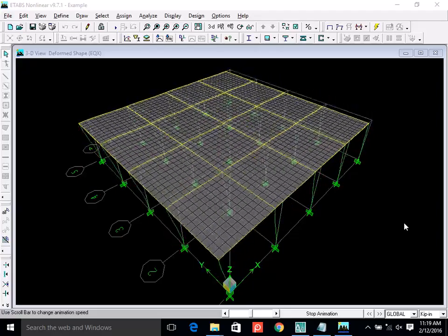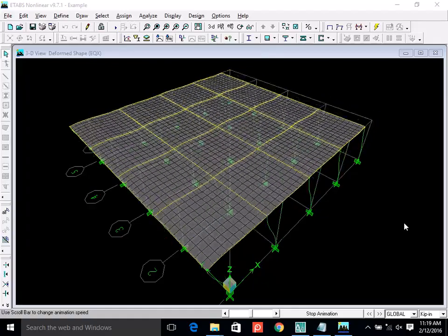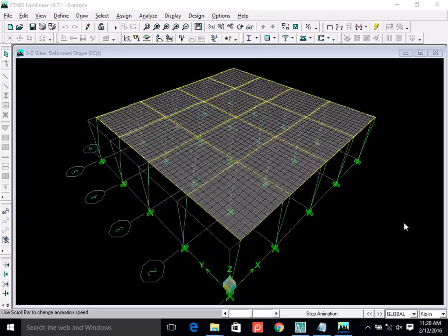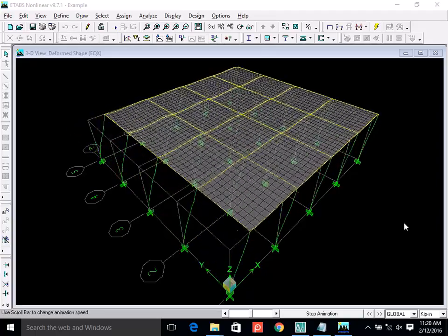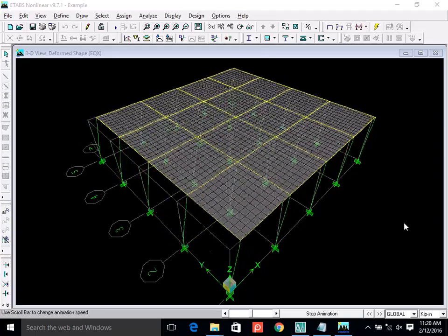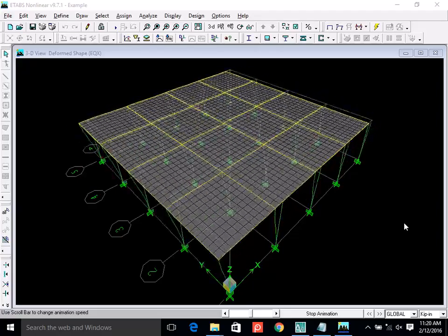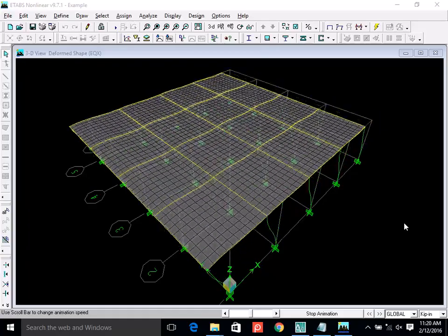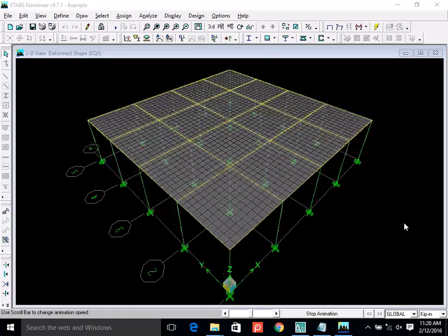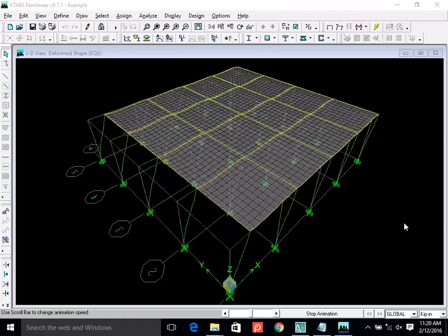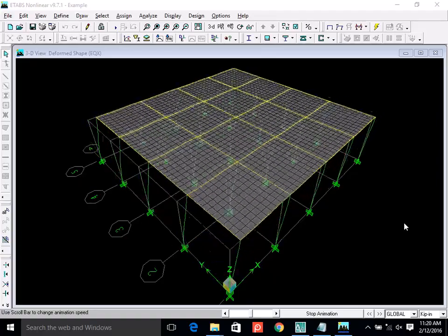So it represents that situation, when the building is occupied and it is hit by an earthquake. For example, if the building is under construction and it is not in use, then in that situation it's only dead load and earthquake. Or for example, this department in the evening has no significant live load, then at that time it's earthquake plus the dead load, including part of the live load, which is furniture, of course.